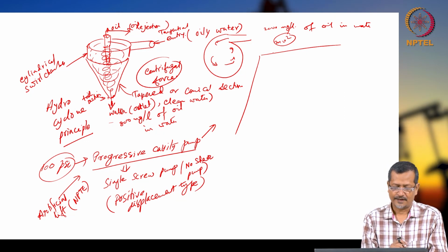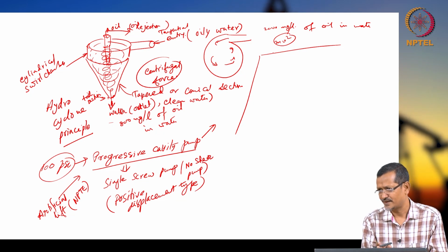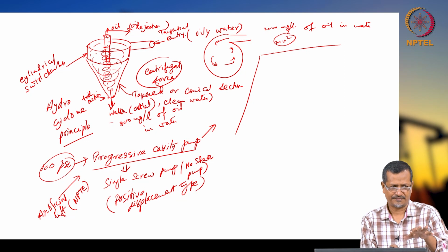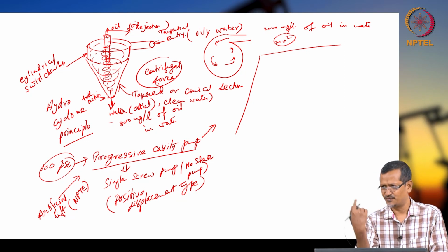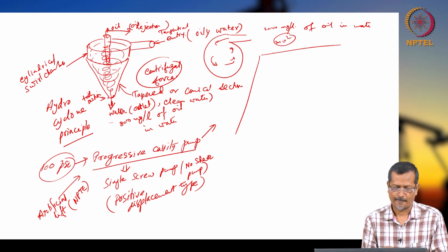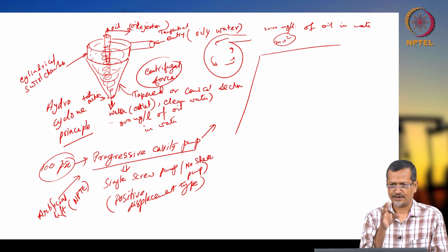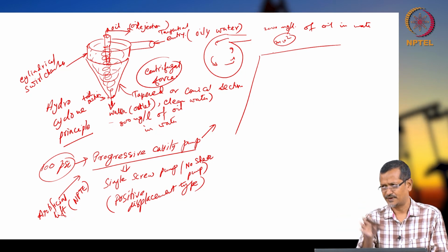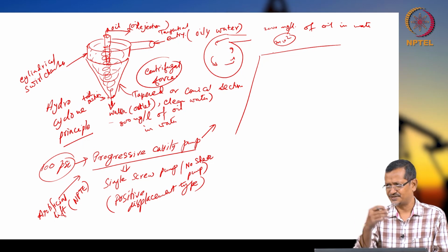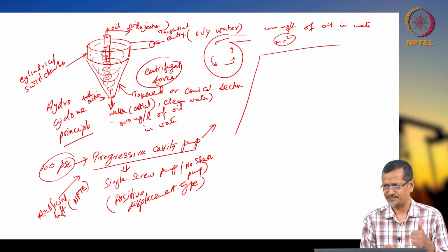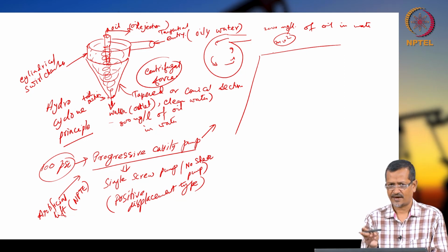Okay. They are insensitive to motion, so it will be suitable for offshore application, like the shaking of an offshore platform because of the wave and wind. So, it is fine, because high velocity fluid is moving and it is separating. They are modular design, so you can use one separator, two separator, three separator, and a very simple design you can see. Only a cylindrical section is there, inlet and outlet is there. So, it is very cheap also, modular design is possible, and they offer lower operating cost if you have higher pressure.